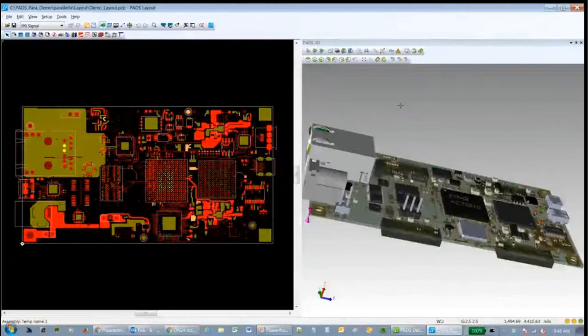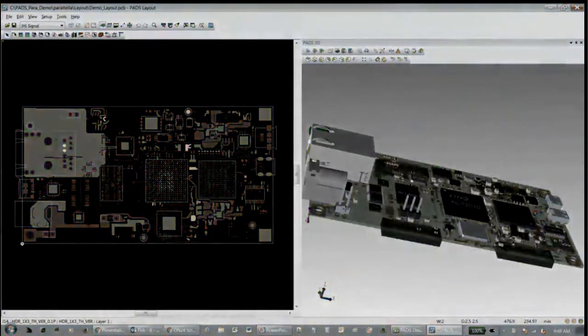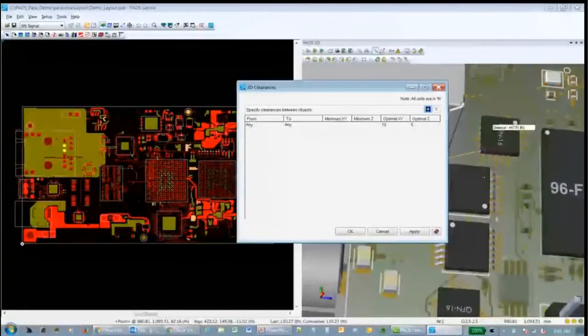And then once you're in the 3D environment, you can obviously place components around the 3D aspects of that design. Look for clearances, being able to do DRC checks. I can measure data here, so I can measure between, say, this surface of this part and this surface of this part. I can get a distance on that, but I can also bring up or set DRC rules where I can actually do dimensional DRCs right in my 3D environment.